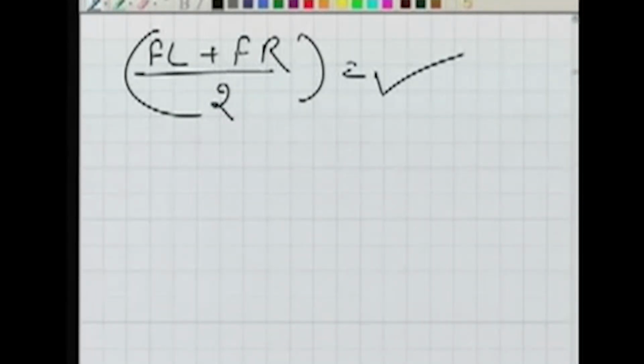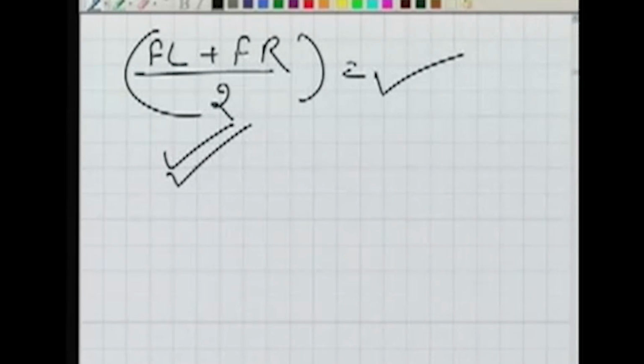So if we take face left observation and face right observation, and we take the mean of that, we will get the correct value, because the error is being eliminated. In one case, the error was positive because we are measuring more angle. In the second case, the error is negative because we are measuring less angle. So we can combine these two readings like this here. So the error can be eliminated. So yes, if at all this kind of problem is there, shift of horizontal wire, it can be eliminated by taking face left and face right observations, and the vertical angles can still be measured correctly.